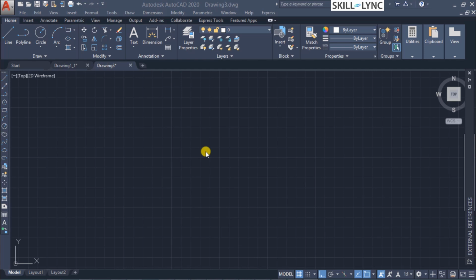This comes into play when you are working with an assembly drawing where multiple persons are working on the drawing. Each and every subcomponent is developed by different persons, but later you bring them all together into a single drawing to produce an output, an assembly drawing. Suppose in the due course one subcomponent gets updated, you need not track back and update your final assembly drawing, but rather it is all carried forward together. That is the external reference.